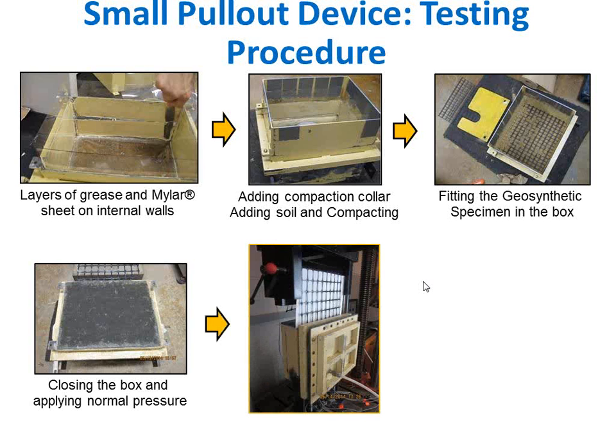Why would we want to do that? Two tests, yeah? We monitor this portion. Yeah, so we get 2 tests for the price of 1. So we get the pull-out response, and at the same time, this is an unconfined tensile test as well.